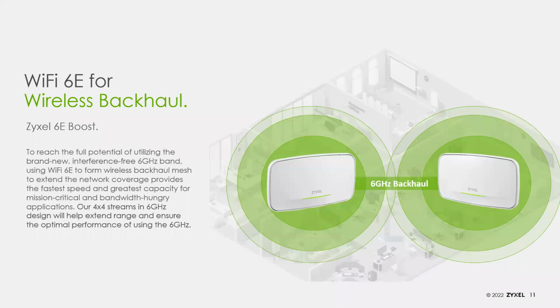Another challenge with 6 GHz right now is that 6 GHz can legally only be used indoors. It may not be used outdoors. The original plan was that the FCC would release the rules for doing outdoor 6 GHz at the end of last year. That didn't happen due to a number of lawsuits. So for the moment, 6 GHz remains an indoor only solution, not something you can use outdoors.